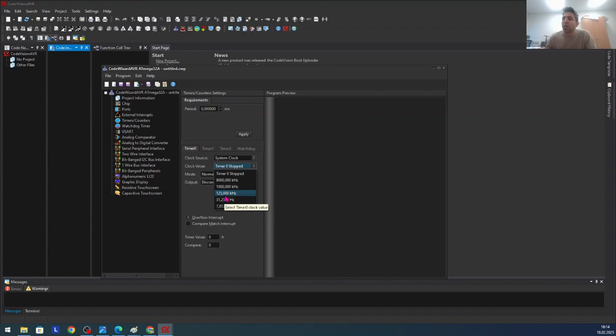It counts with, for example, if you use prescaler 2, it counts with every 2 pulses of the microcontroller's CPU, only 1 clock for the timer. If you put, for example, 256 to be the prescaler, then with every 256 pulses from the CPU, the timer will count only 1. It will count only 1 step forward.